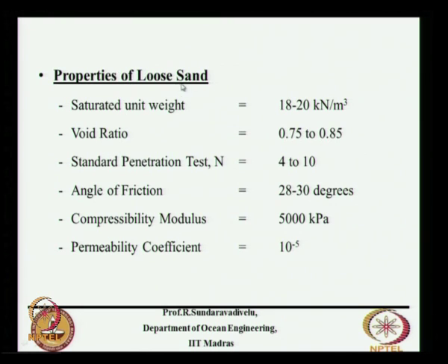Between clay and sand we have silt. Silt also will liquefy during seismic condition. So if the silt is there, especially if you have an atomic power plant and all, if you have silt or loose sand, the value is less than 10, you have to necessarily do the ground improvement, then only you should put the foundation, because statically you may be able to satisfy the design, but dynamically during seismic condition it will become a quicksand, whatever you are doing the whole thing will go down.